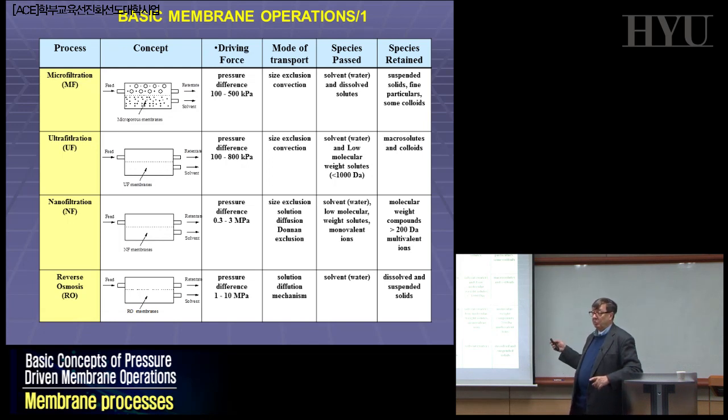because you always have to reproduce a system with a thickness of 50 microns, 180 microns, where 1 micron is the surface, the same thickness, otherwise you are changing the fluxes, and with no defects, no pores, otherwise salts are going across. So it took about 30, 40 years to be able to produce this. But now you have big companies producing this membrane, running day by day, continuously, supplying membranes, not sufficient for the request of the market.